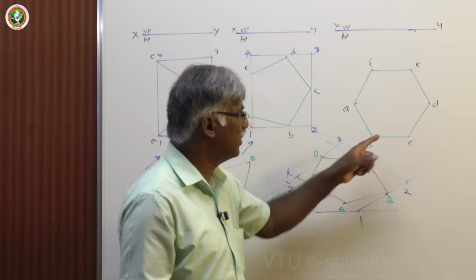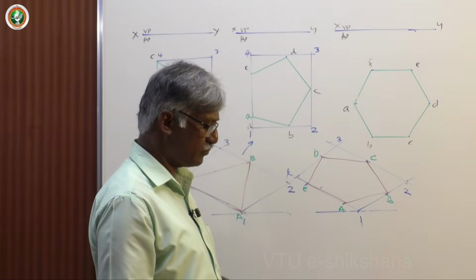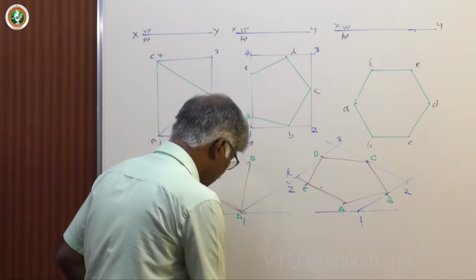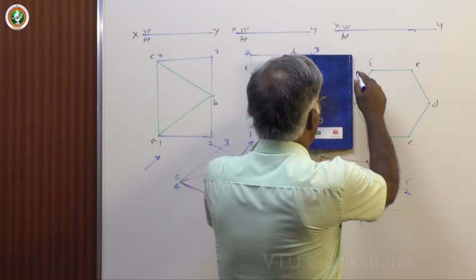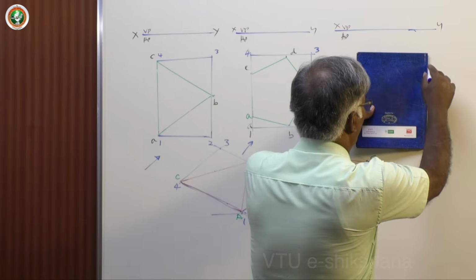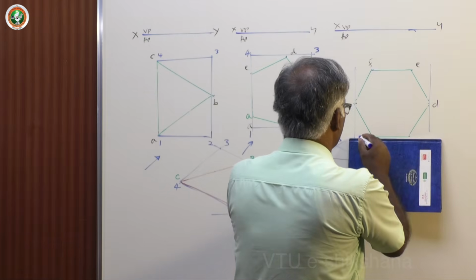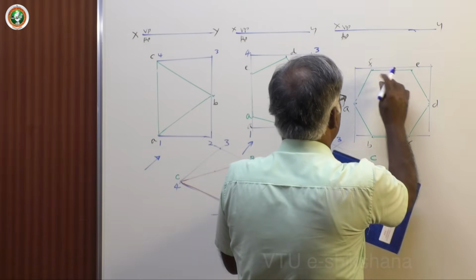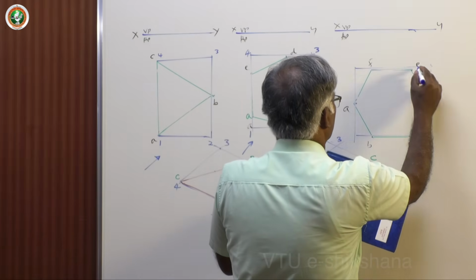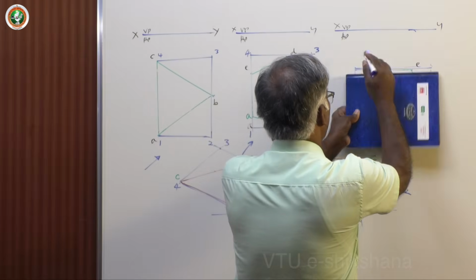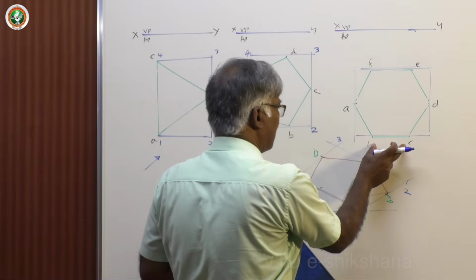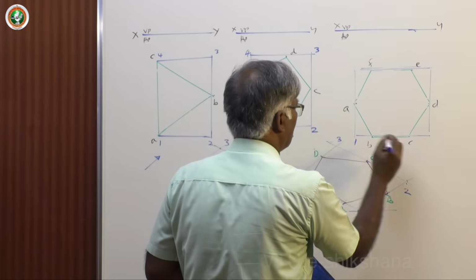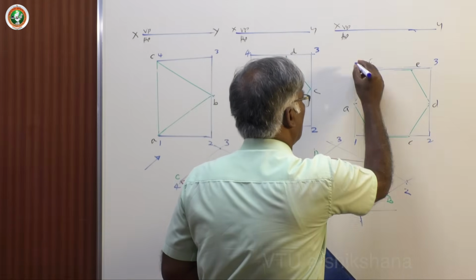Next comes the hexagon. For the hexagon, again mark the box. Yes, here the longer side is actually 2 times the side. So that is the characteristic feature of the hexagon. Okay, so this is 30, say this becomes 60. Okay, total. So this is 1, 2, 3, 4.